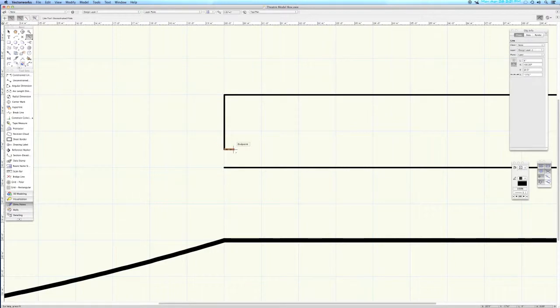inches. I'm going to draw a rectangle. That snapping to that line is 6 inches. I'm going to make it a little bigger and make it 9 inches. Again, I'm having a little bit of trouble getting to it, so I'm going to tab 9, tab 9. That didn't exactly do what I wanted, but I can drag that down. Okay, the reason I drew a rectangle is that it makes it easier then for me to draw an arc.